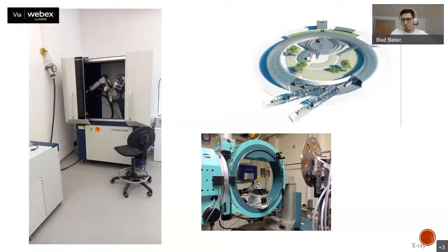Okay, sir, I have another question. Can we perform XRD analysis for non-crystalline materials, such as amorphous, and can we detect the elements it contains? Sorry, there was a little bit of distortion. So if we can use XRD for non-crystalline samples? Yes, we can measure it, but we will not get sharp peaks from it. We will get really broad peaks.